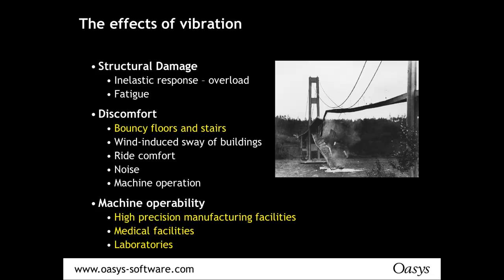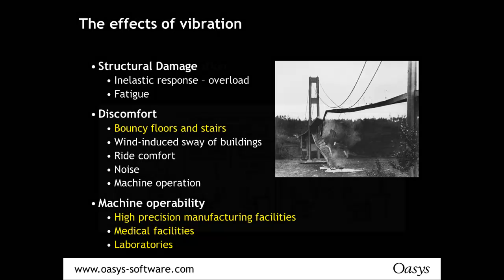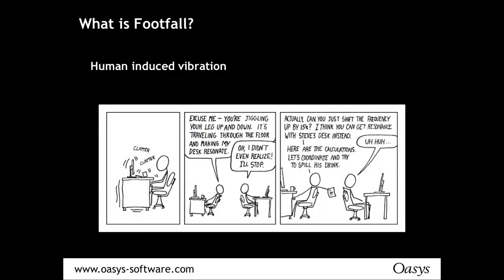Now, footfall vibration, looking today, really covers a subset of those. So footfall is a serviceability analysis which can be annoying to people, or it can interfere with your facility. So it could vibrate your screen.